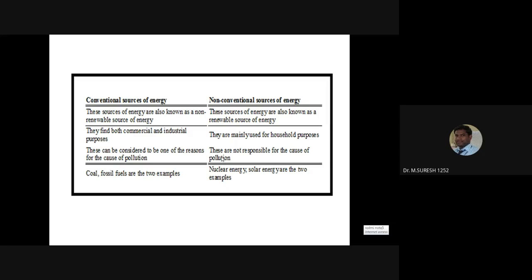The exhaust gas recirculation method can be employed in both diesel engines and petrol engines, and we can also use it for supercharged and turbocharged engines. Depending on the supercharged and turbocharged engine, we have to focus on maintaining the temperature level in relation to the engine design factor. Then we can also go for a catalytic converter. Those methods are mainly used for controlling NOx emission. Again, I am telling you how to control NOx emission by controlling EGR. EGR is nothing but exhaust gas recirculation.